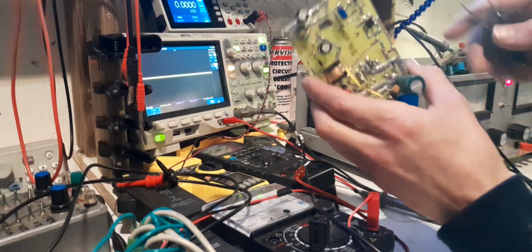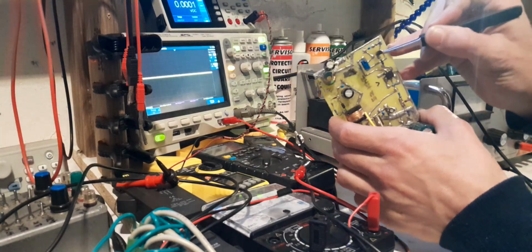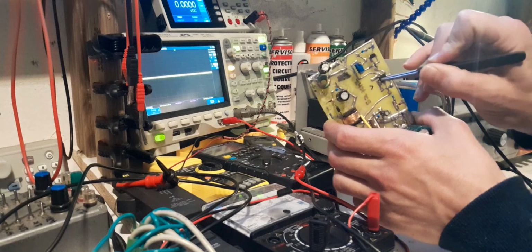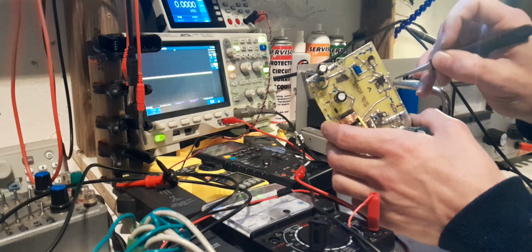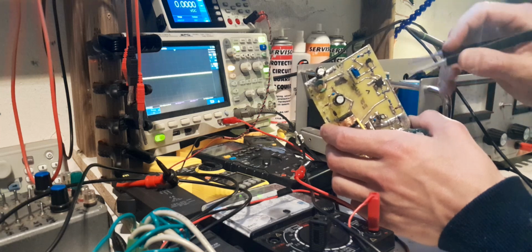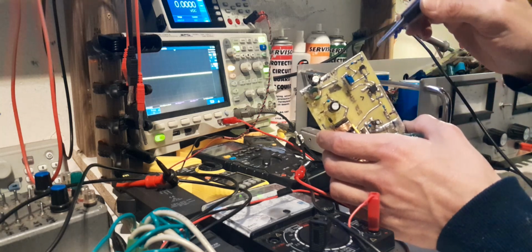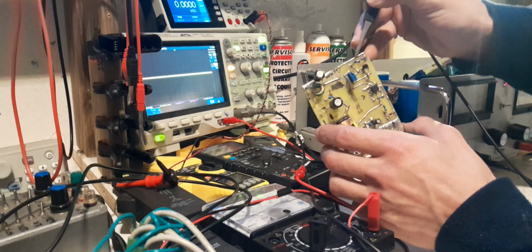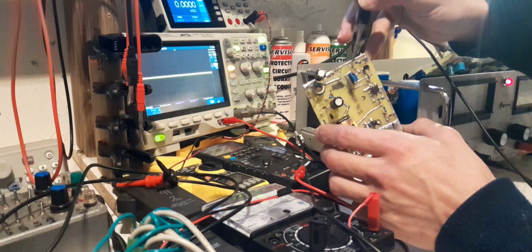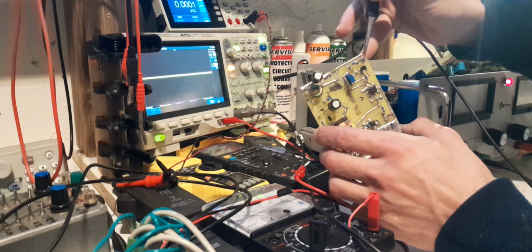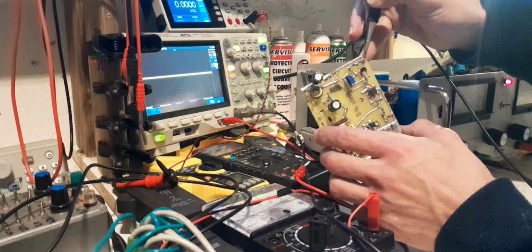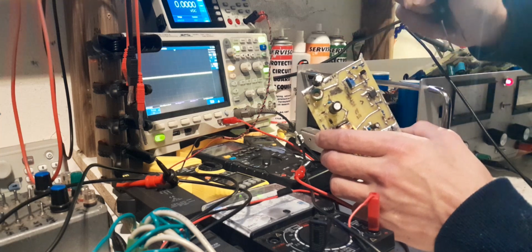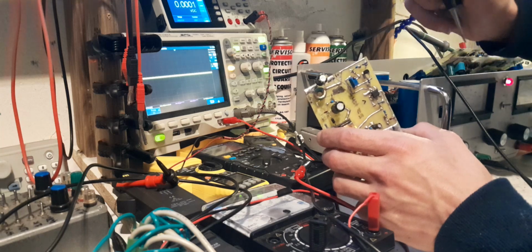You might notice that there's a TL431 here, going to a 3-terminal opto isolator, so it's got the base pin pulled out. But anyway, that's not what the interesting part is here. You might notice that there's a little compensation snubber network in between the reference pin and the anode, or is that the cathode? I'm not sure.